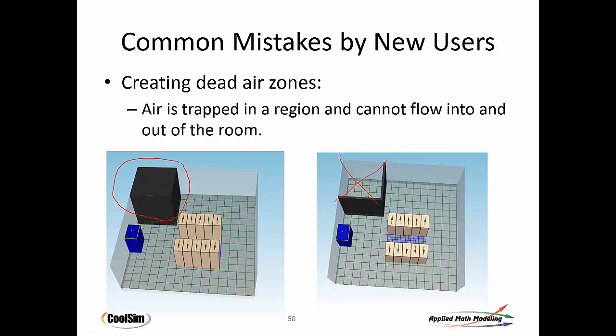So the better thing to do is block it out like this. This means there will be no mesh in there, which improves your solve time, reduces your solve time, and if you're not interested in what's in there, just block it out. If you are interested in what's in there, use baffles and let them leak just a little bit, and you'll get the same effect, but the solver will be able to solve it.